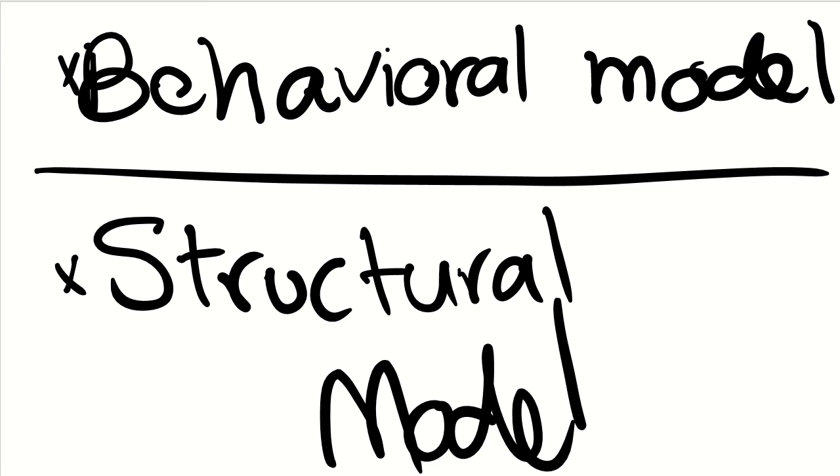Another way of programming is a structural model. This means that when you write a code, you specifically specify connections. Remember, this is all about designing hardware. At the end of the day, you want to connect multiple blocks inside the FPGA.